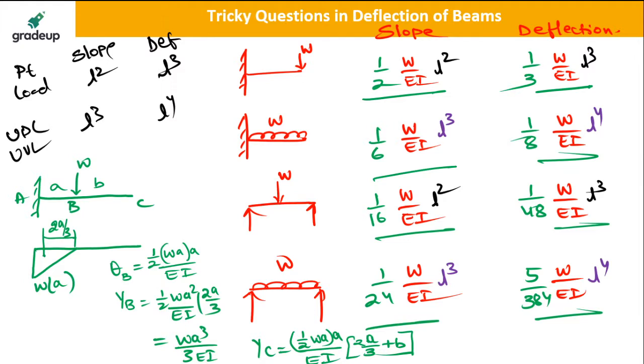Yes. Next, proceed for the shear center. What do you mean by shear center, my dear friends? So generally in the beams of C section, C channel, L channel, you see that there will be some twisting because of the loading on the flange. Is it clear now? Loading on the flange. So because of that loading on the flange, there is nothing in between to balance that twisting. So we have to apply the shear force at a point so that you get an anti-clockwise couple to balance the clockwise couple developed. And that point is called as shear center, my dear friend.